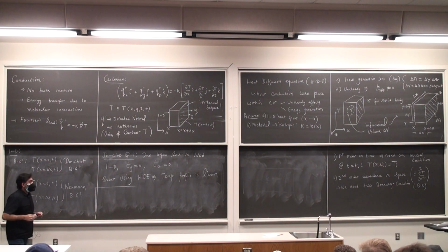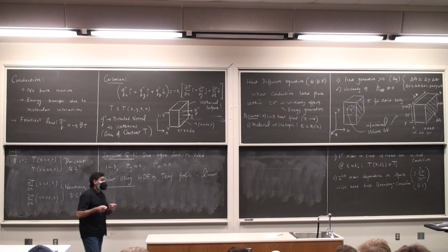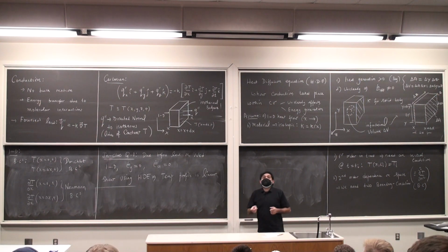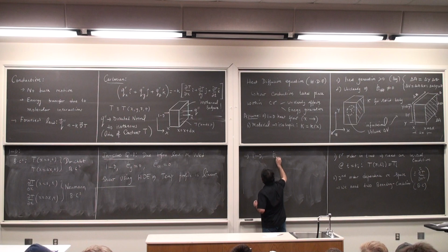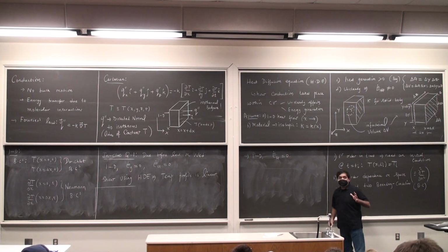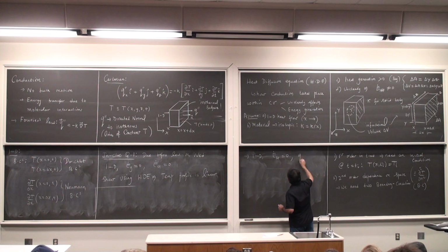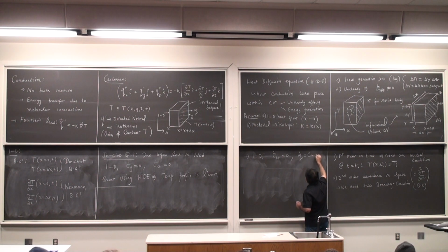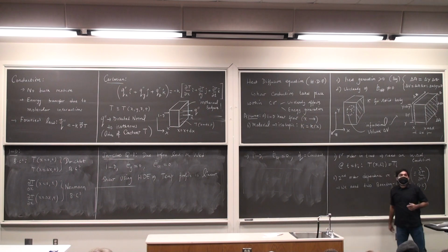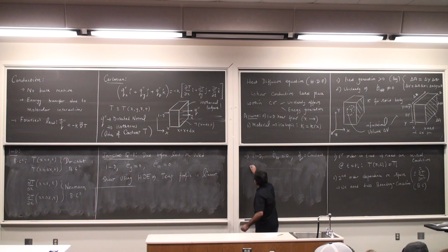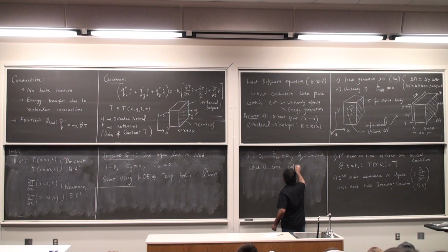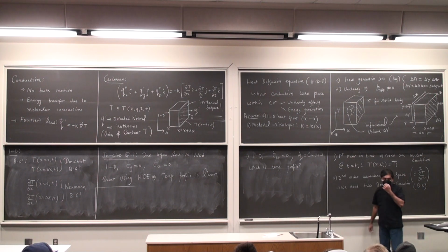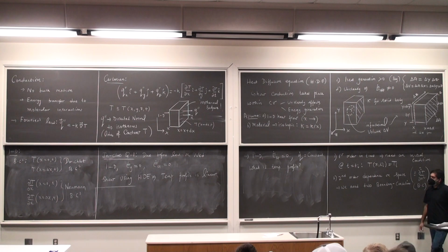So, I'm going to consider the situation of steady conduction, but in the presence of constant energy generation. So 1D, E dot stored is 0, so I'm assuming steady, one dimension, and I'm assuming that Q dot is a constant. What could be the temperature profile? Temperature profile across the body.